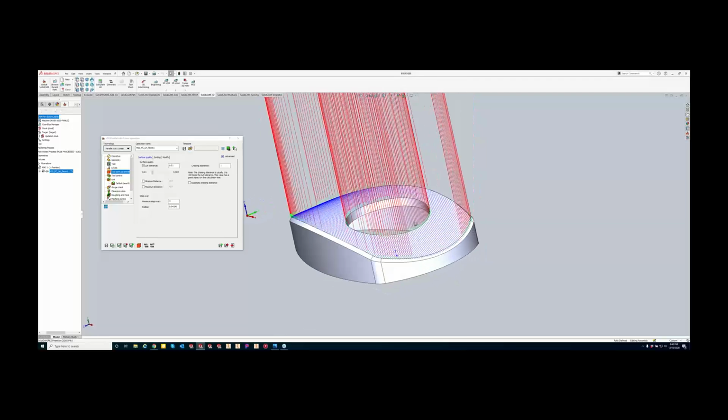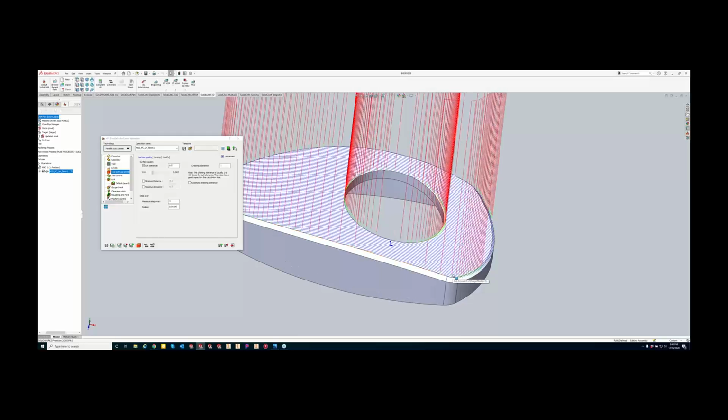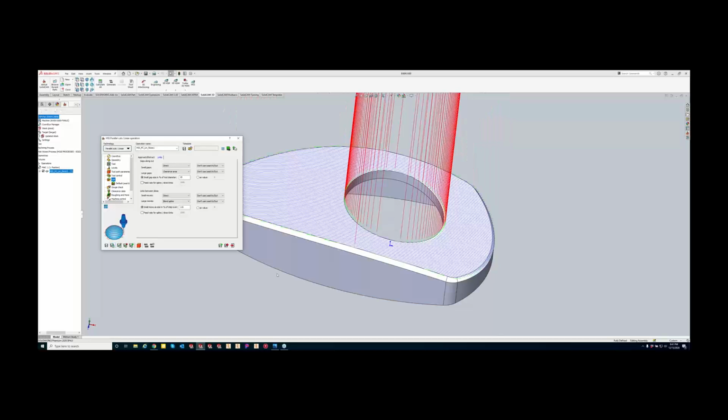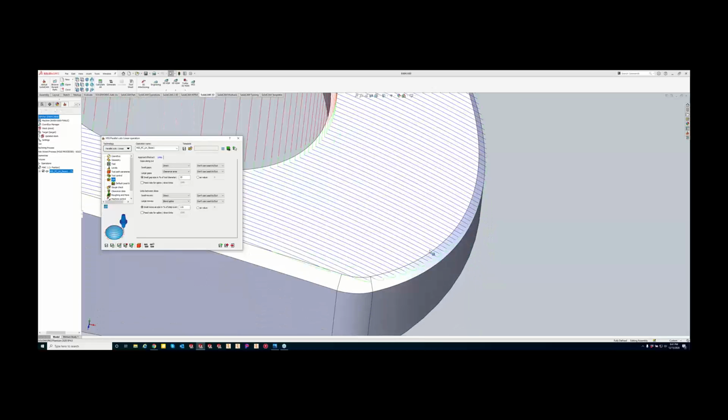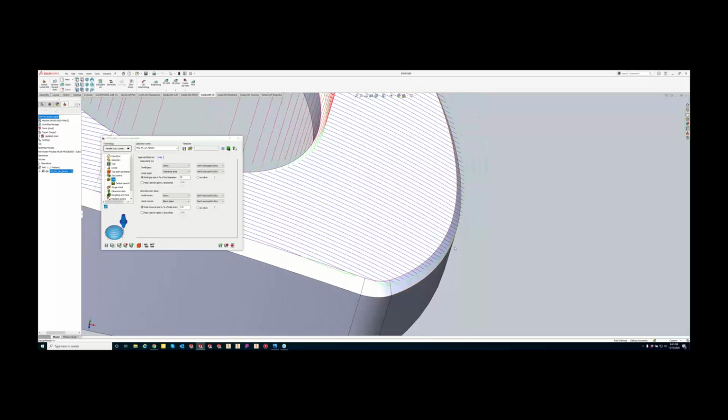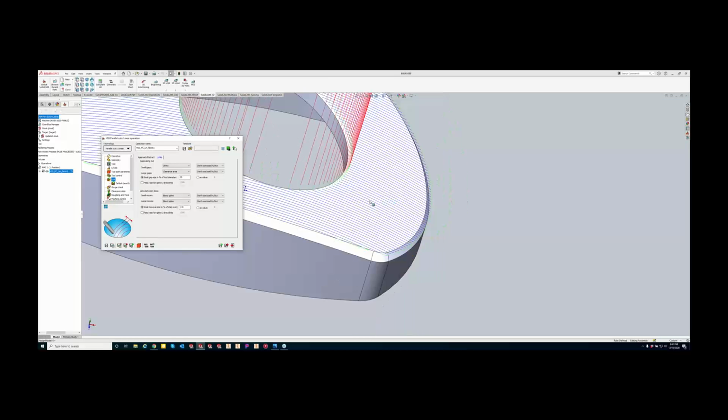So now we can see, well, one, we have a lot of jump ups and jump downs between our slices. So let's go to our links. And our slices, instead of going to clearance, we're going to do a blend spline. So now that took care of all the outside edge ones. If I just want to double check, I can zoom in and see it. I can see a couple smaller ones here. So just to be on the safe side, we'll do a blend spline for everything. So now every single one, we got a nice arc going through there.